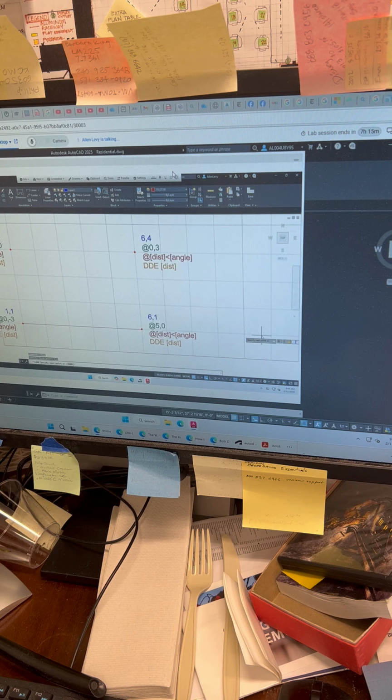If you remember from when we set up our drawing, we had the angle direction and the angle start. So it was 0, 90, 180, 270. So that's the angles that we're talking about here. All right, so this is going to be at 0 degrees. Now I need to get to here. So this is in the 90-degree direction. And the length of it is going to be 3 units.